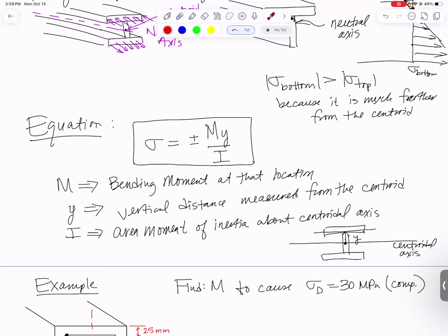Remember, we can do table lookups to find the moment of inertia of these rectangles about their own centroidal axes. But then I need to use the parallel axis theorem to get them all collected about the same uniform centroidal axis of the whole shape.